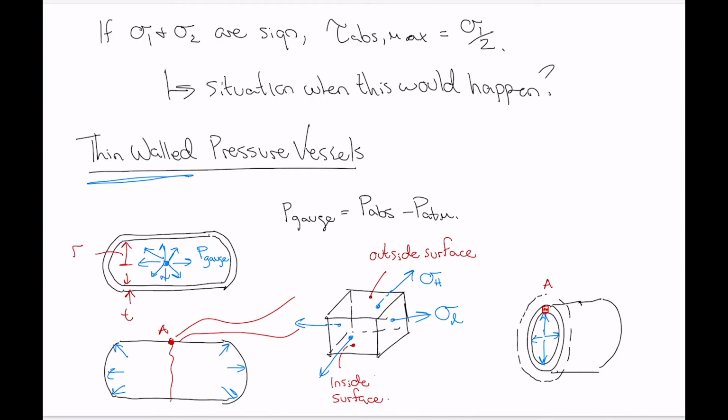So if I just draw that back in here, sigma R goes to approximately equal to 0 if the radius over the thickness of the tank is greater than or equal to 10. So that's the thin wall assumption. So the tank has a thin wall.